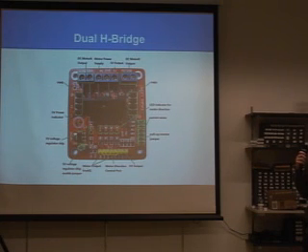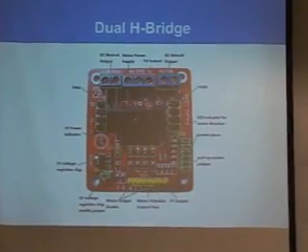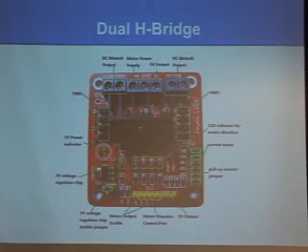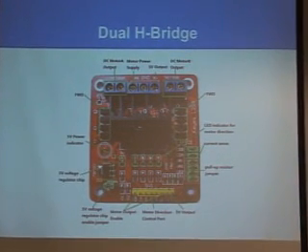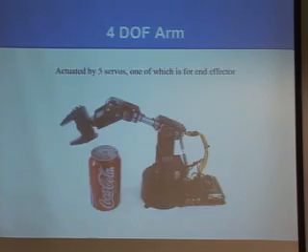This is the H-bridge. It's pretty simple to use. We have the PWM signals inputted from the bottom yellow ports, and then the motors are connected to the top blue connectors, and we have power coming in from the middle.